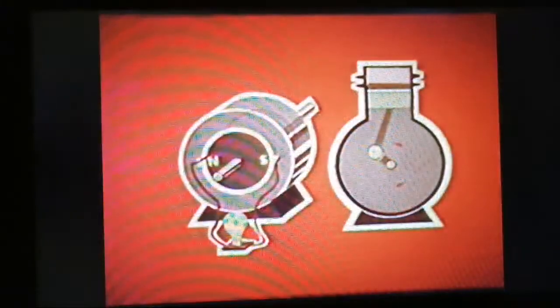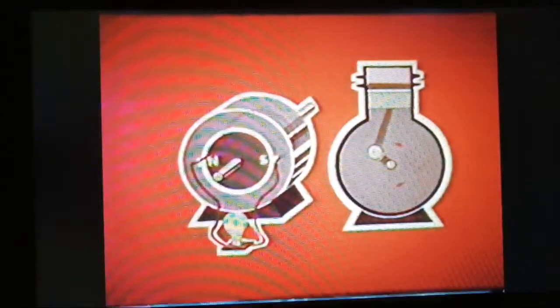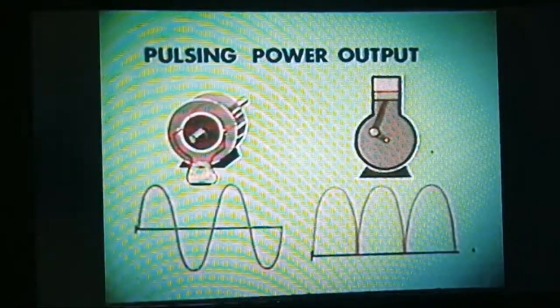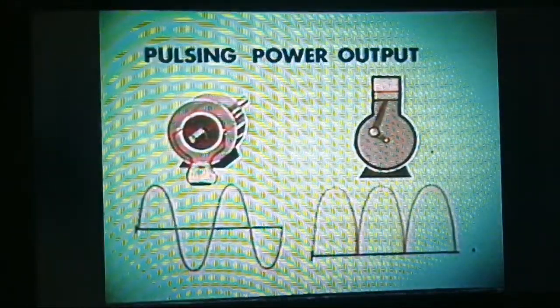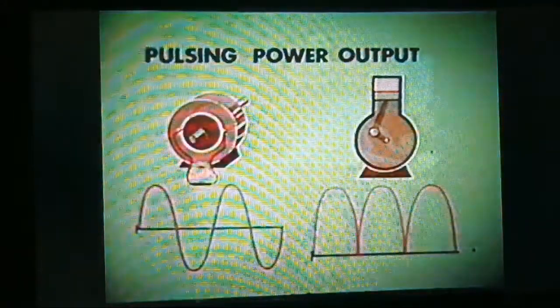The single-coil, single-phase generator, like the 1-cylinder engine, is not very practical for producing large amounts of power. Both produce power in spurts or pulses. Obviously, smoother power output is desirable. So let's solve this problem electrically instead of with cylinders. We'll assemble 3 single-phase generators on a common drive shaft.